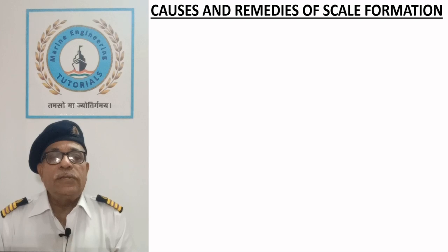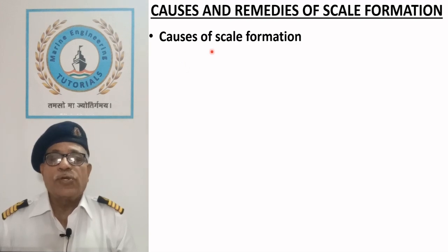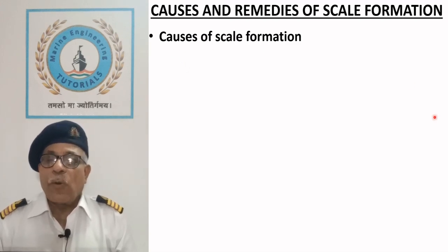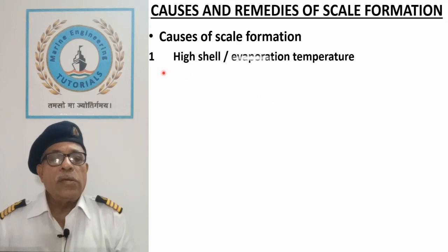Causes and remedies of scale formation. Causes of scale formation. Scale may deposit in the evaporator tubes due to the following reasons: high shell or evaporation temperature.